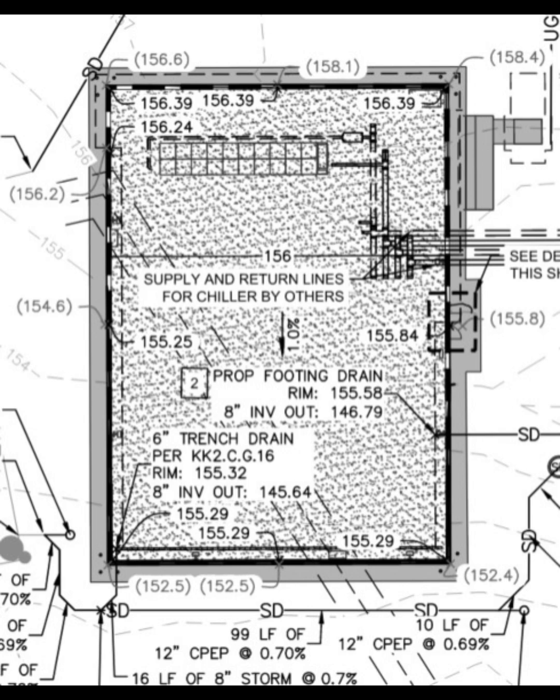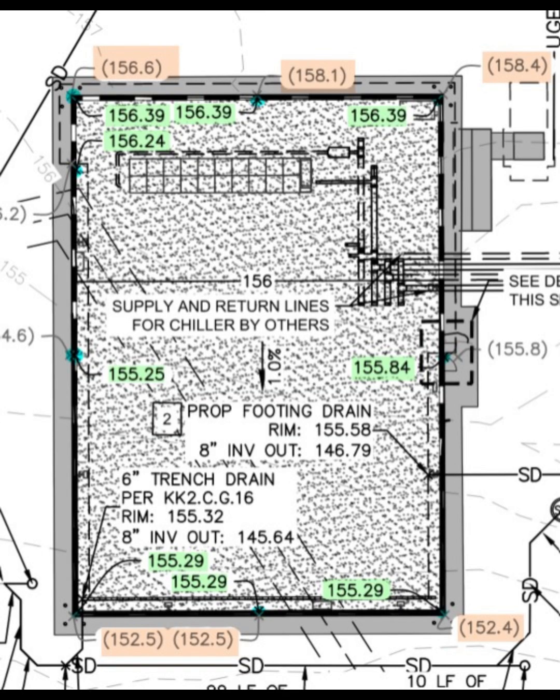This is the grading and drainage plan. It shows the planned elevation for the corners, midway, and important benchmarks like the entry gate threshold on the center right of the concrete slab on grade. The orange colors are the existing asphalt elevation of the parking lot surface. All numbers are feet above sea level. The new elevations are the green highlighted numbers. These are for the top of the slab, TOS.